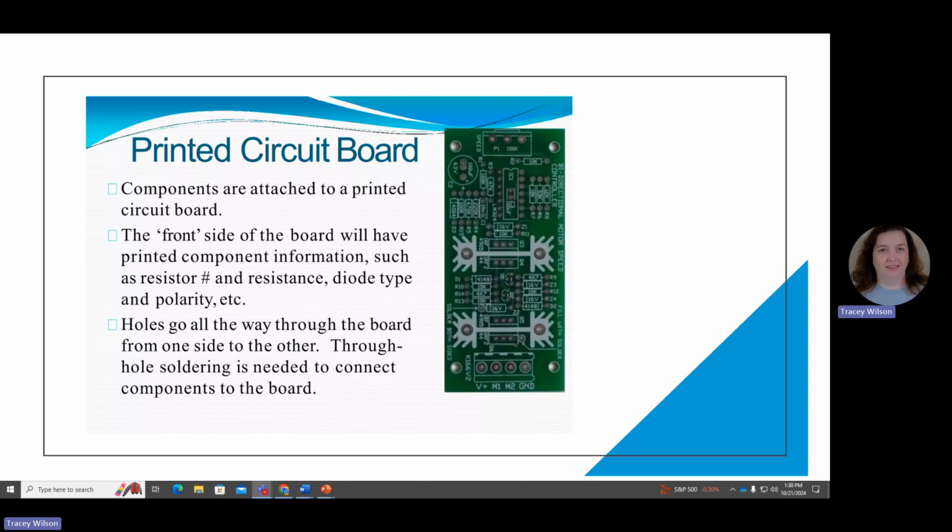Because it's really easy to touch two of those wires together or to accidentally put it in the wrong slot. Those pins are incredibly close together, and if you're like me and have vision problems, incredibly hard to read the labels on some of them. So always make sure your wiring is correct before you start applying power.